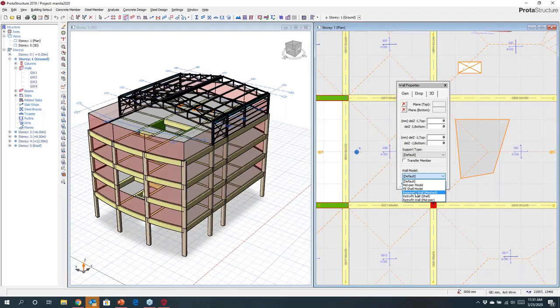This is where the basement mass would participate in the superstructure, while the building above wouldn't. And then the second analysis where the building above participates but the basement doesn't. And you would automatically have different R factors for those situations, and you can consider those in one analysis run